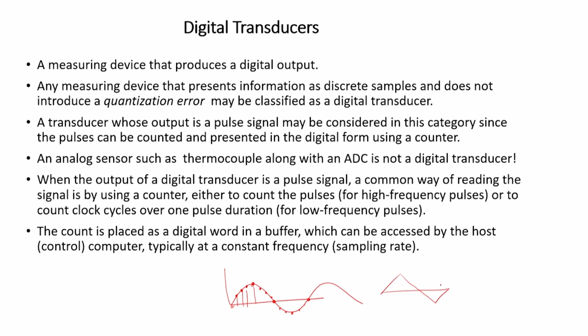So, if you have at least 5 of them, then it shows a digital signal which works like this. You get at least some periodicity, but still that would not reveal the true picture. If you get more number in between these, then you can gradually build up that no, it is not a linear variation, it is a nonlinear variation, and similar like that. Okay. So, that is the quantization error that you have to avoid with the help of the sampling points. So, these are the certain points that you need to keep in your mind from the analog to digital conversion